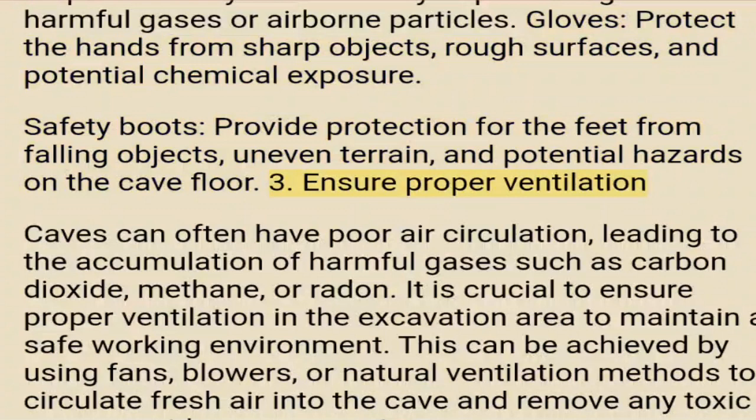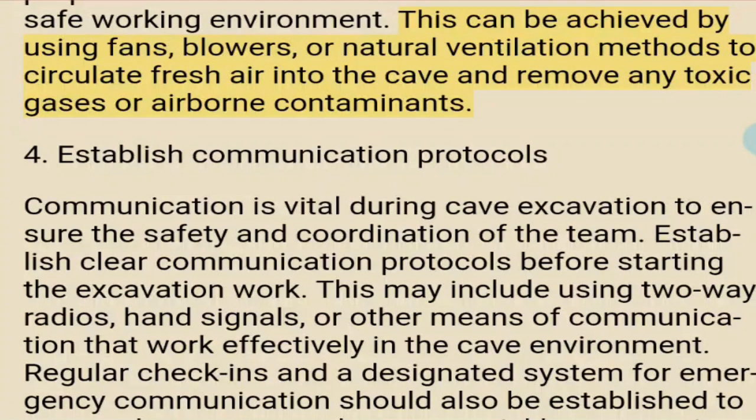3. Ensure proper ventilation. Caves can often have poor air circulation, leading to the accumulation of harmful gases such as carbon dioxide, methane, or radon. It is crucial to ensure proper ventilation in the excavation area to maintain a safe working environment. This can be achieved by using fans, blowers, or natural ventilation methods to circulate fresh air into the cave and remove any toxic gases or airborne contaminants.